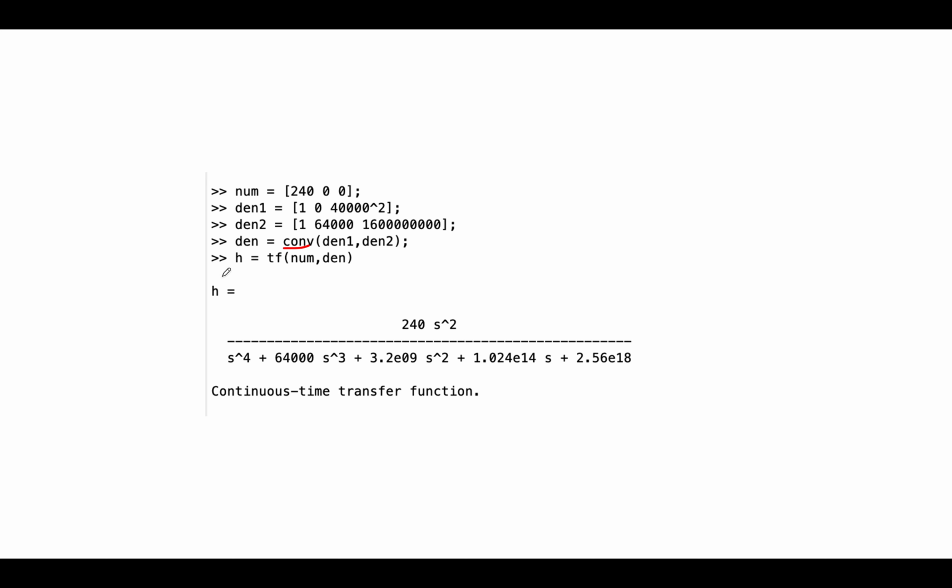Next week is all about transfer functions, but I think you get it that in MATLAB, in order to generate this polynomial, you have to define it as a transfer function. Do you have to generate the polynomial? No, you don't. It's just kind of useful, and the reason it's useful is it allows you to look at your function and make sure it looks like you expect it to look.